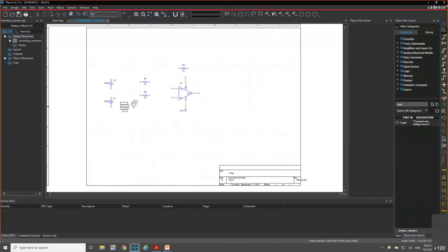Depending on what simulation you're going to be running, you need to provide a different input voltage. So some simulators allow you to change your voltage source. PSpice has broken it down into separate voltage sources. So VSIN gives you a sinusoidal transient voltage source, whereas VAC will allow you to run AC simulation. So now we have the sources.